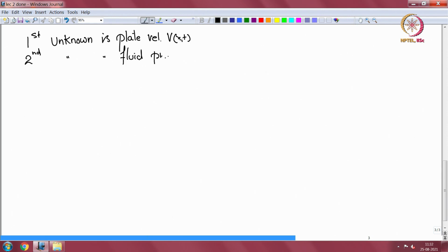So this is one-way coupled. Why is it called one-way coupled? Because the velocity that you have found does not change anymore. The velocity decides the pressure. The pressure in turn cannot modify the original velocity. That doesn't happen.